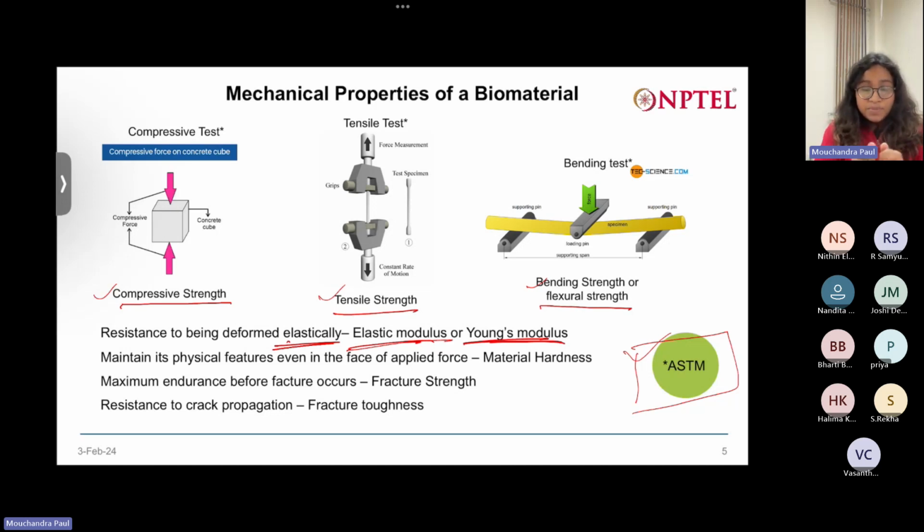So when you expand it, it will increase in length, and when you release it, it will become shorter. So remember, elastic modulus is always defined when we are trying to elastically either increase or decrease length, meaning cause elastic deformation, and as a result of it, the material is trying to resist it. Okay, I'll come to it a bit more when we discuss Hooke's law and all.